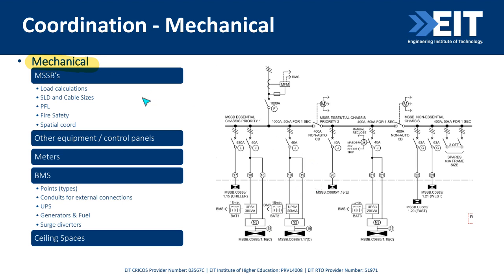They might have various control panels located around for bespoke equipment that just need a power point. We need to know, are we going to meter their power supply to these mechanical switchboards? Or have they documented meters in those switchboards? Because there's no point in paying for double metering, but we need to make sure it's one or the other.